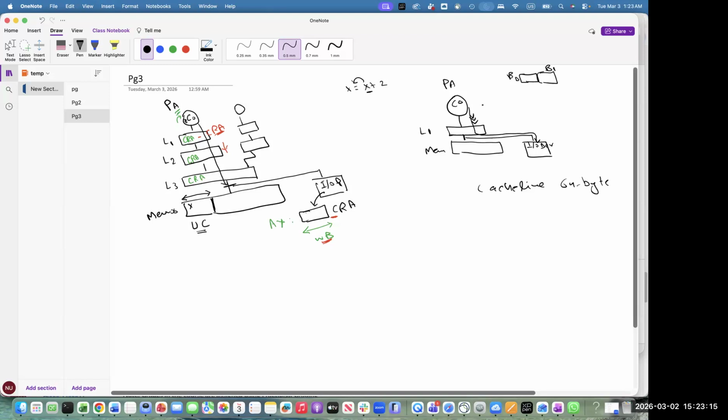So what to do? Inside the core, you have a store buffer, right? When process A produces B0, you don't send it to the system bus, you put it in the store buffer. Then B1 is also placed in the store buffer. You wait until the buffer is full.